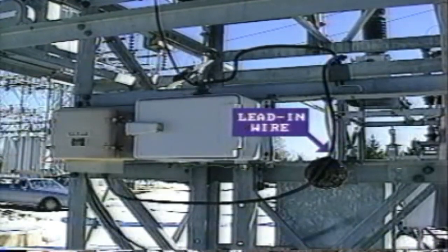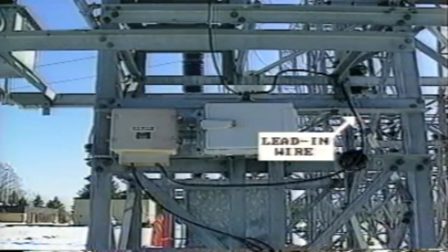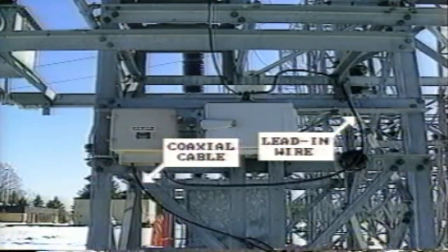The lead-in wire may be supported on insulators or run in PVC conduit. It may even be run in metallic conduit, but this is not good practice as the capacitance of the wire to ground will be larger in metallic conduit, and this extra capacitance could affect the tuning action of the LMU. Check the lead-in wire for corrosion, burn marks, or tracking, particularly where the wire comes close to the metal structure or cabinet. Next, examine the coaxial cable.